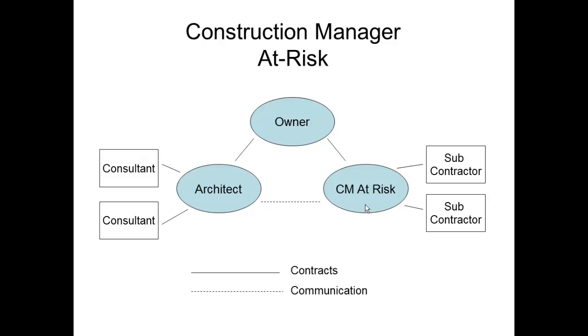They would then come in and sit in on the design portion of the project, and bring up to the design team any issues that they think might need to be changed, because the construction manager at risk is going to give us a GMP during the final phases of the design. They'll be giving us budgets throughout. We'll be looking at doing some of those value engineering items during the design process.